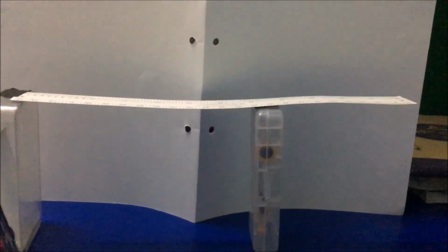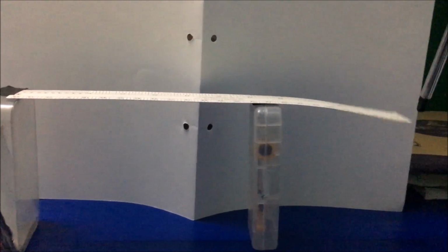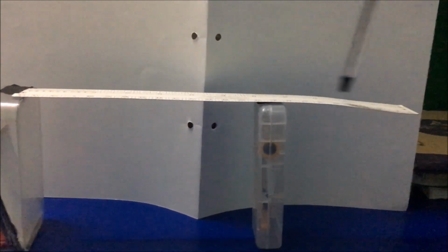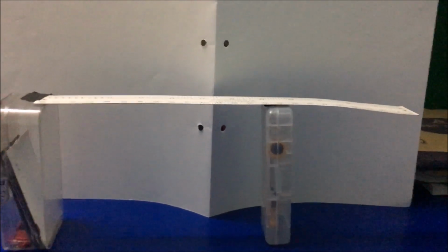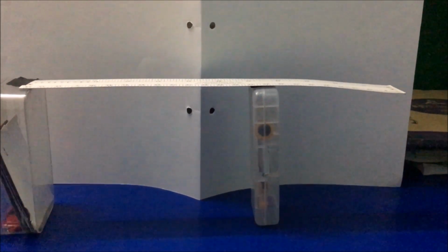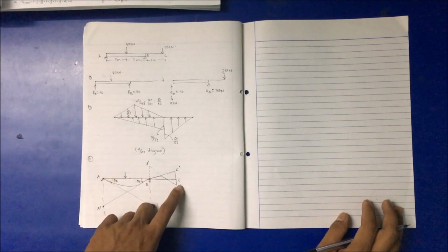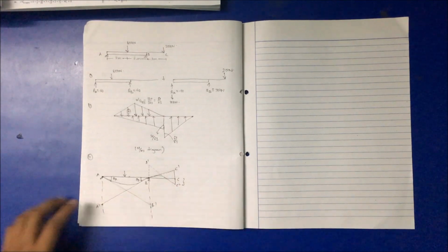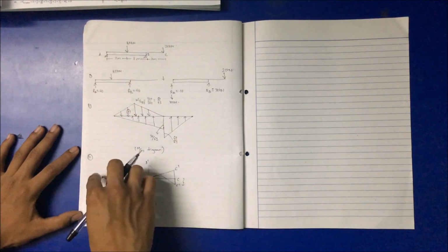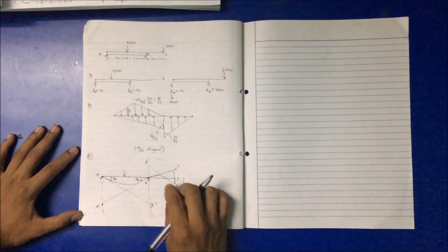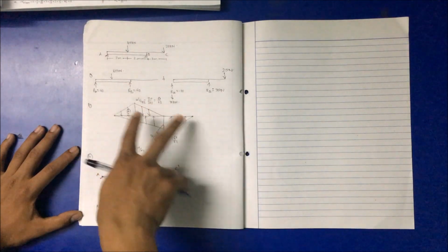Now for the second case, we'll apply the load at this point, so it goes down from the mean point and a deflected shape occurs in this way. So this is the illustration of the application of load. We have to find theta A, theta B, and the deflection at point C. For that, let me determine, as I have already said, BB dash and AA dash, which represent the moment of the M by EI diagram from A to B at the respective points.